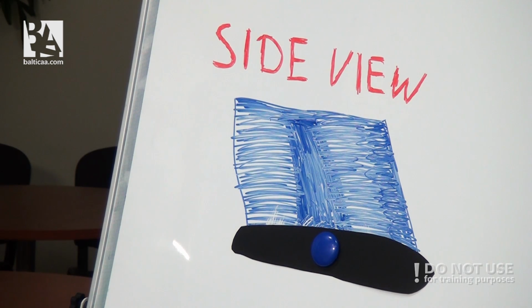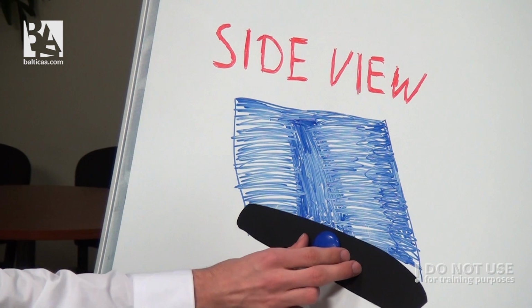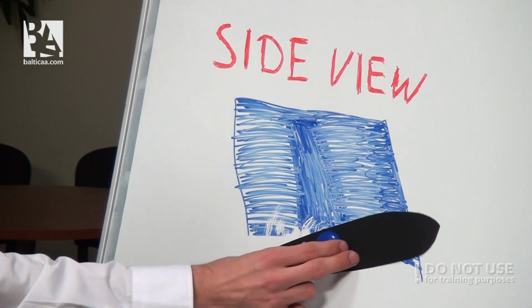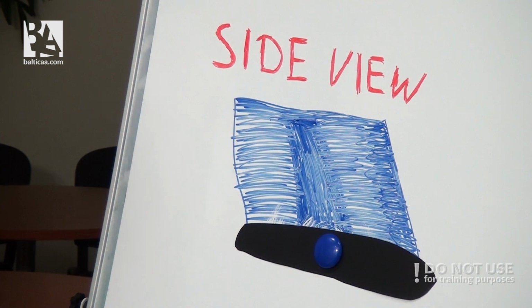If your airplane is equipped with a stabilizer or an all-moving tail, the entire surface will move and your angle of incidence will change. This is good for several reasons. For example, we will have a larger CG range, we will have less drag, and you will always have the same control authority. It is used on modern large jet airplanes.